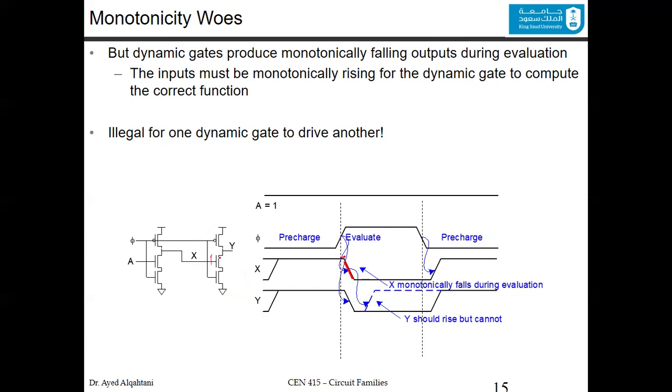So it was 1, and this was connected, and this also was connected. So it will drop the whole charging of the output Y to the ground and makes it 0 for a very brief moment of time. Now what happens? You are expecting to go back again because of the same problem. Y is now 0 and it cannot be charged during the evaluation session at all, and it will remain 0. And now it's even worse than before. So what should we do to fix this problem?